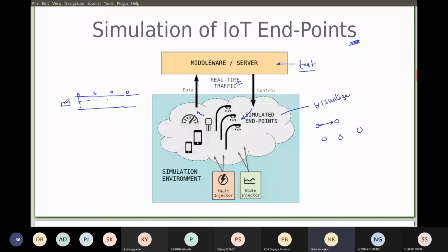That signal is sent to the server, and then the cloud platform will send commands to the neighboring street lights to turn on. So when this particular light senses that there is a vehicle coming, it turns on, and the next few street lights also turn on. That will be a useful thing. So there is a sensor value going from this street light to the middleware, and then a command going to neighboring lights to turn them on.